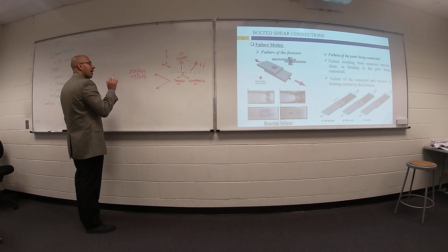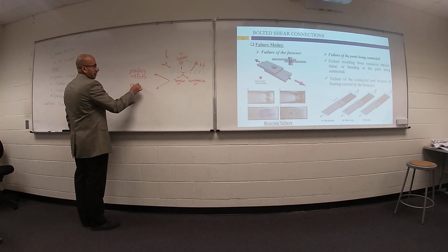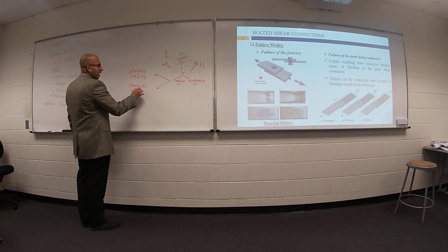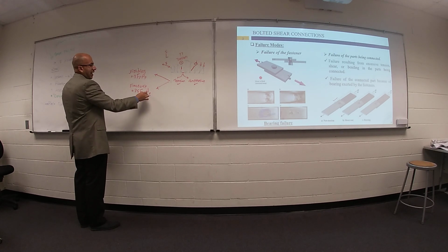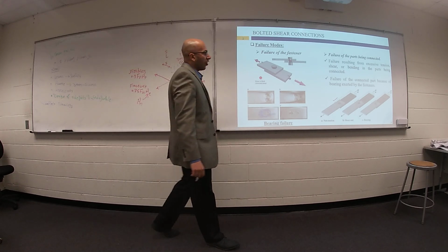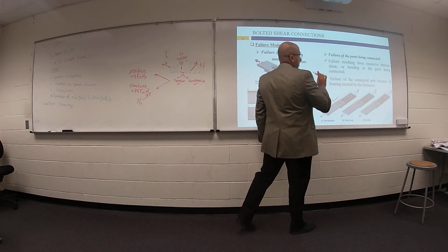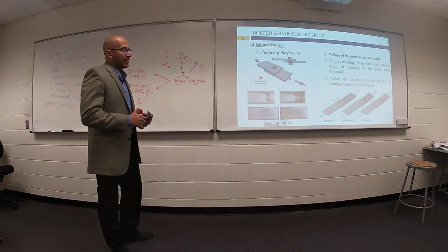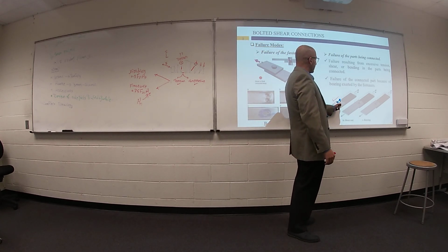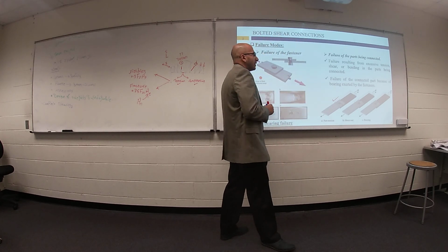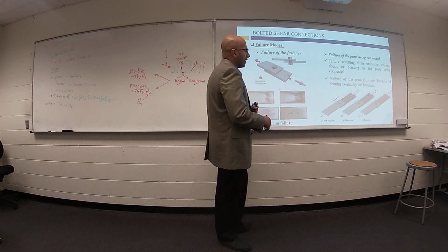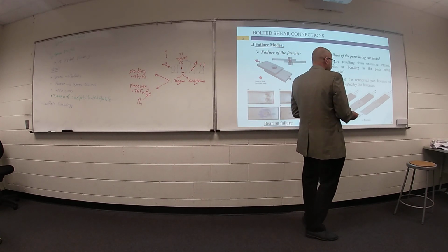Second condition, we need to avoid fracture of your member. So 0.75 F ultimate area effective, and this area effective comes from area net, to avoid this mode of failure. In the net area, maybe the effective net area, we need to avoid this kind of fracture in the material of the connected members. The second one and third one, we will talk about today.